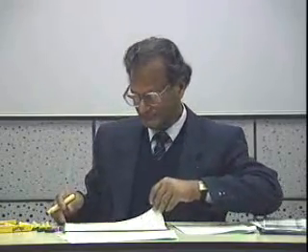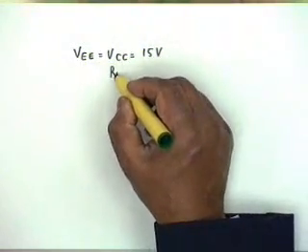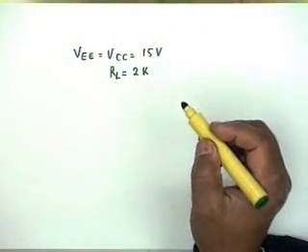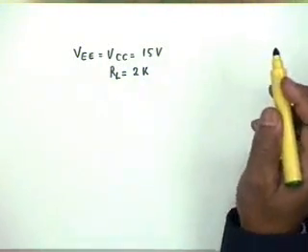Now, in this problem, what is asked for is the following. Please follow this carefully. Have you been able to draw the circuit? Totally? Okay. What is being asked for is the following. Let VEE equal VCC equal 15 volt and RL is given as 2K. First, you neglect the effects of the 25 ohm protection resistor for normal operation. That is, the 25 ohm protection resistor is not there. First, ignore R16.